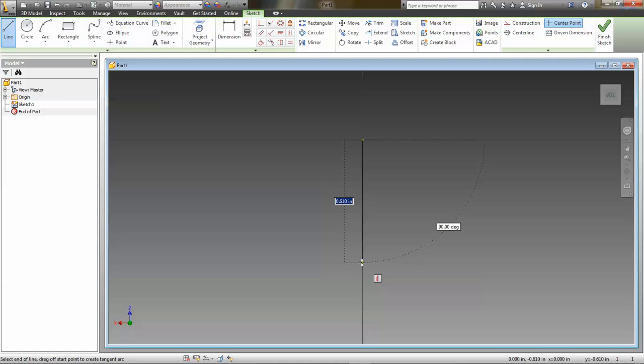First of all, the overall height is 0.325. Now, the diameter of the peg is going to be 0.0625, and we're making half of that, so I want 0.03125, 90 degrees. Then this comes up 0.25.